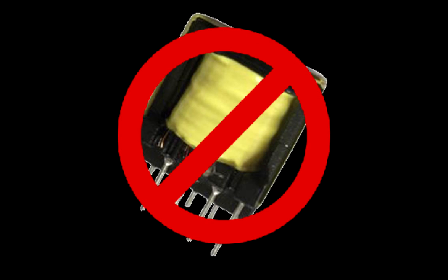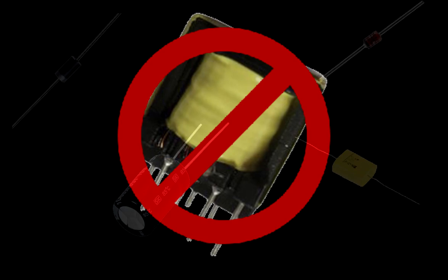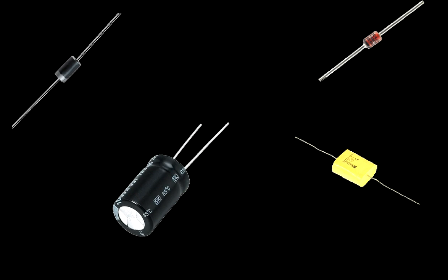So if we want to get those values without a transformer, we have to use other electrical components that give us the possibility to rectify the voltage and also manage a specific value of voltage no matter which input voltage we have, because we need a power supply that keeps 5 volts in any case. At this point, we introduce the rectifier diode, Zener diode, ceramic capacitor, electrolytic capacitor, and resistances in the development.